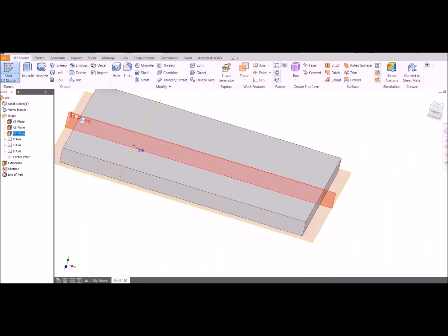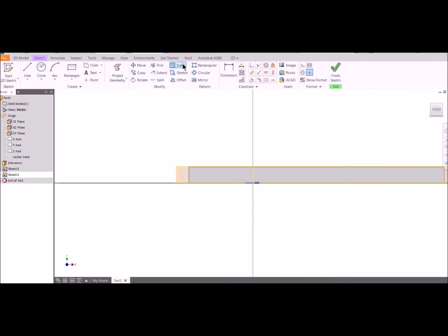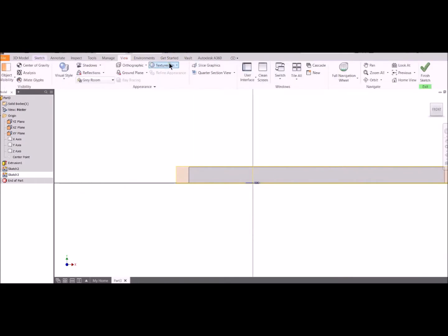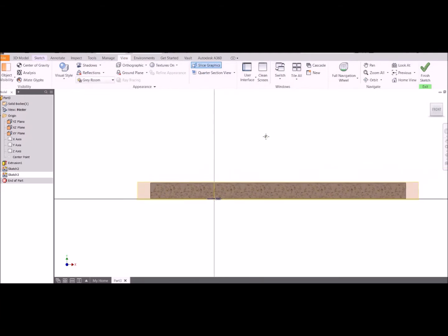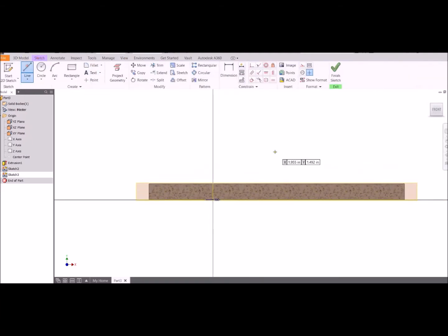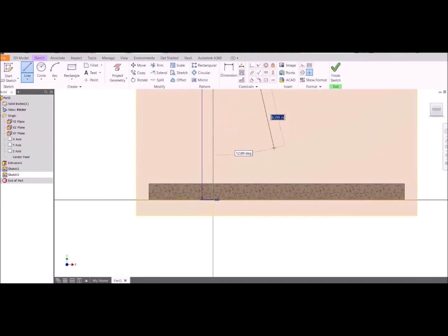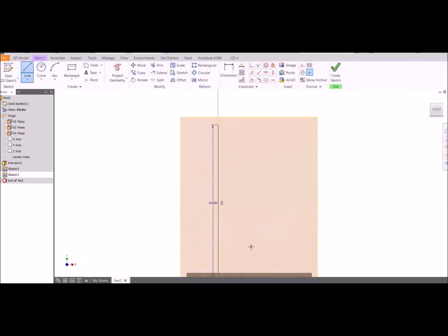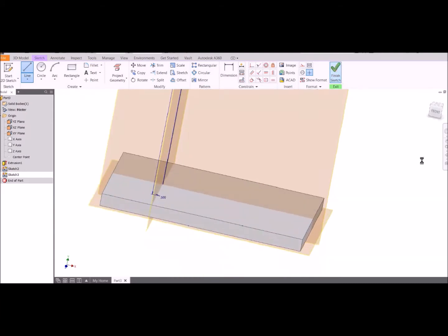Now I'm going to create a sketch defining the path we're going to use to sweep that circle along. Slice graphics allows you to see into the inside of something if you're working on a plane that bisects a solid. I'm going up 10 inches. Again, this is the path that we're going to use to extrude our circle on. Now over 5 inches. You don't have to use my dimensions, but anyways, down 1 inch. So here it is, looks kind of like a hangman's noose.